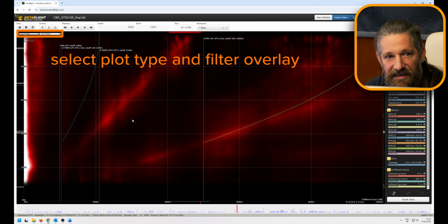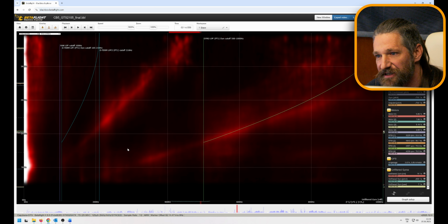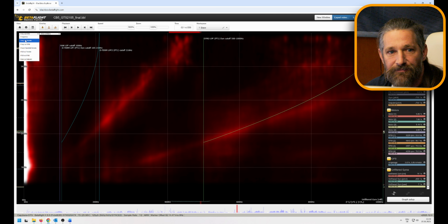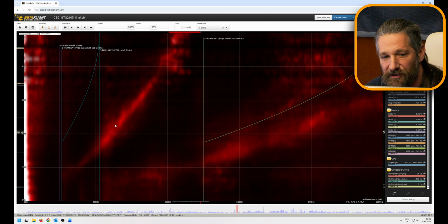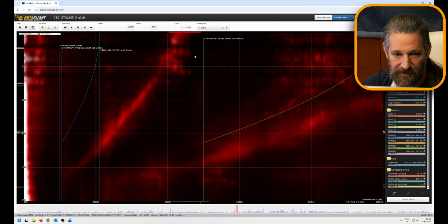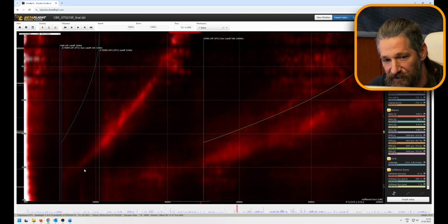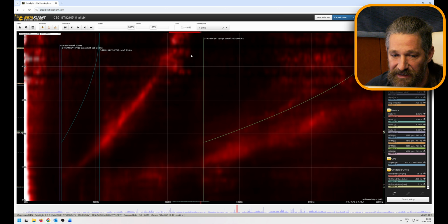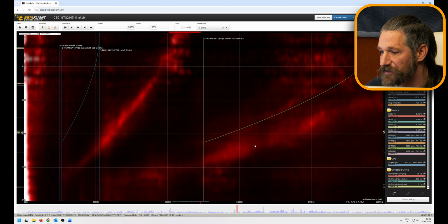If you want it clearer, you can set frequency versus RPM. It should be a linear relation. Whereas with throttle, you will see the props don't spin up the same at different throttle values. So at low throttle values, the props need longer to spin up, so you have less torque over here than you have over here.